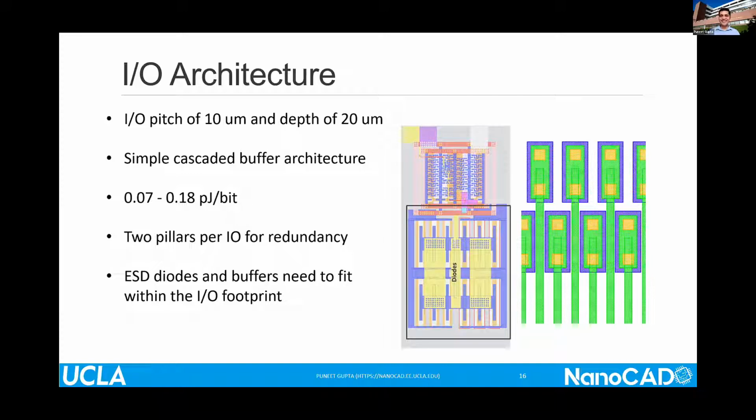So yeah. And what's the speed of these IOs per line? They can run at up to 4 gigahertz, but we plan to run them much lower, about a few hundred megahertz. What's the link length, the max distance they traverse? Max distance is 100 micron interdie resistance plus, let's say, 100 micron buffer on each side, so about 300 microns. Got it. So the bulk of the cap is not there. The bulk of the cap is actually in ESD.